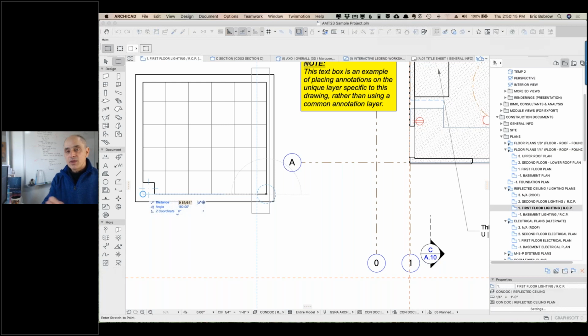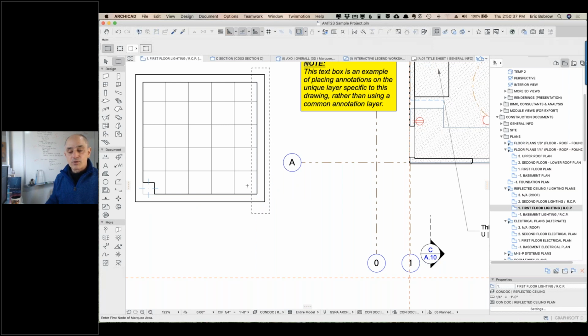So that says go in that direction, but go back a certain distance. So you put in the distance, in this case 10 foot 0, and then a minus. And if it was in metric, you could say 3.5 for meters, 3.5 minus. And now it's moved exactly that distance. And I hit enter. And we now have a very precise distance.